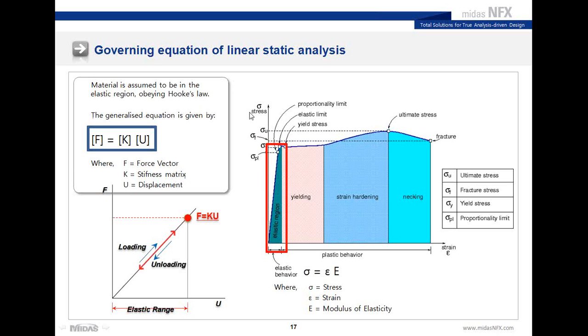And this equation is obtained from the material curve you see on your right, and this particular zone bounded by the red box is the elastic region for the material, up to the yielding point, where the stresses and the strain increase proportionally, and are equated by this factor E called modulus of elasticity, which is a characteristic of every material.